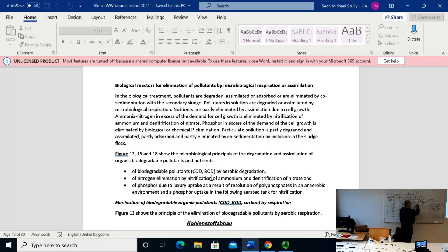And take the nitrogen out of this ratio, and assimilate is about 2 grams, is this ratio 2.5 to 0.5, maybe 2.5 to 3.5. Then you get this assimilation by 80 grams of degraded COD of 2 grams nitrogen assimilated, 0.4 grams of phosphate. And if you multiply that by 7, which is about the ratio for nitrogen as TKN to proteins, then you end up with 14 grams, which is about 50% of the volatile suspended solids.